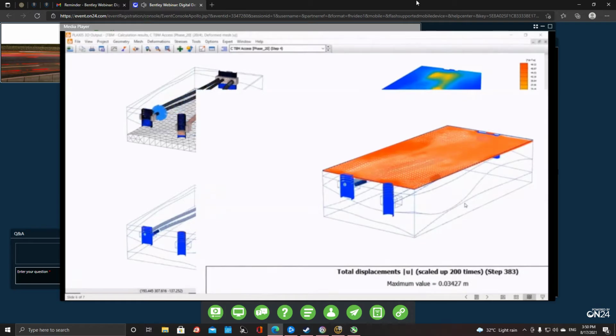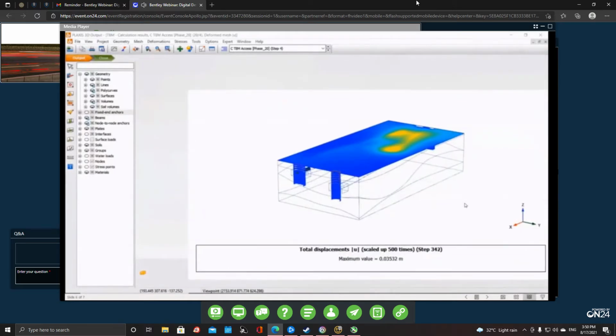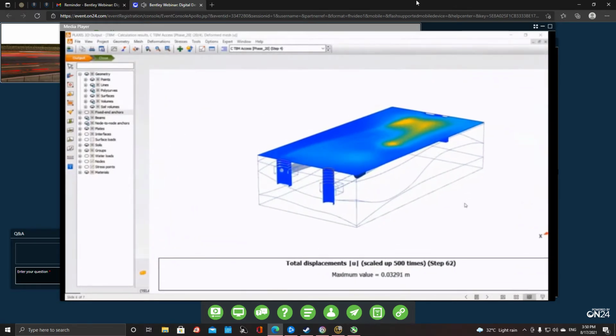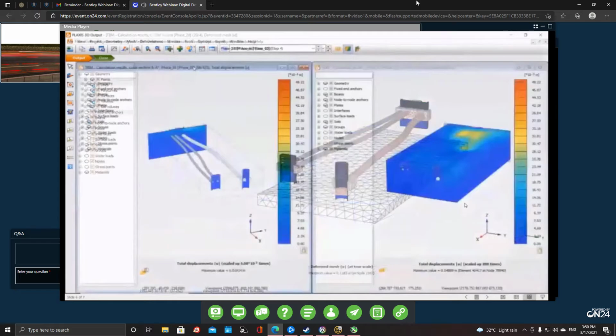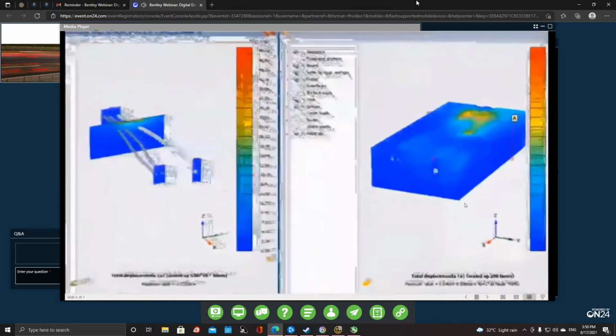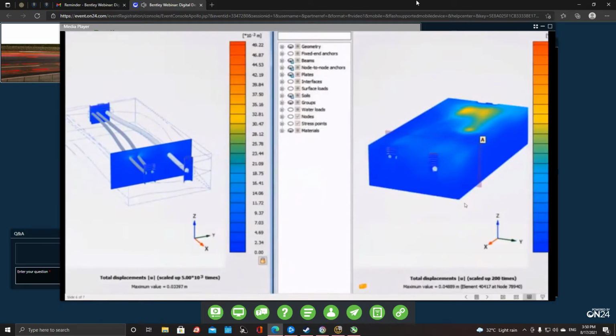Upper right shows the displacement field of the model throughout the stages. From there, we can see it is critical at the early stage of the advancement due to adjacent tunnel effect, which then mellows down over the distance. And here is just a close look of the deformation behavior at the ground level in the heat map kind of representation. And this is how the powerful post-processing algorithm restores the three-dimensional reality at high resolution.